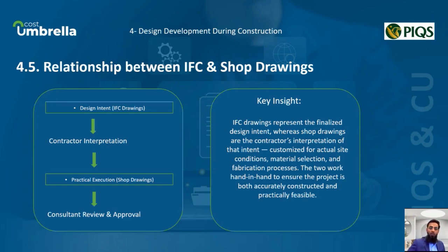The key insight here is that IFC drawings and shop drawings serve different yet complementary purposes. IFC drawings answer what needs to be built, showing the end goal and design intent from the designer or engineer. Shop drawings answer how it will be built, adapting the intent based on real-world constraints and construction methods.